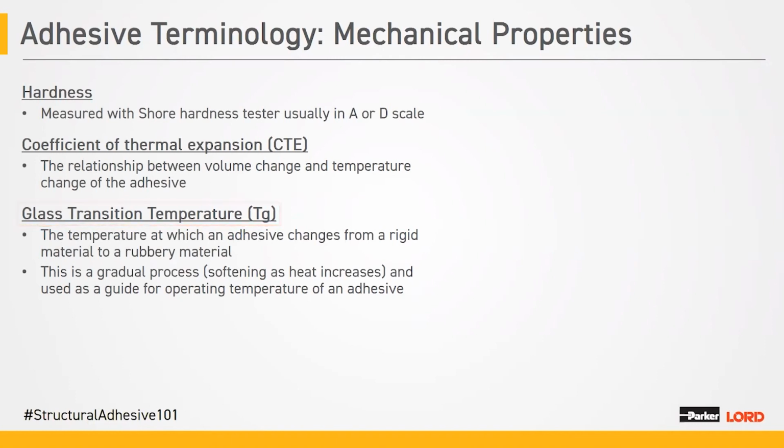Think of this more as softening on thermoplastics. So it's a range of temperatures, not just an absolute. It's often expressed as a single temperature value, but know that the softening occurs over a range as a gradual process. The best example to think about is if you're thermoforming plastic parts, knowing that the material will begin to sag or begin to reach that rubbery state at one point of temperature, and when it's finally used, it may have to reach a second temperature where it's more elastomeric, more stretchy to do the vacuum form.